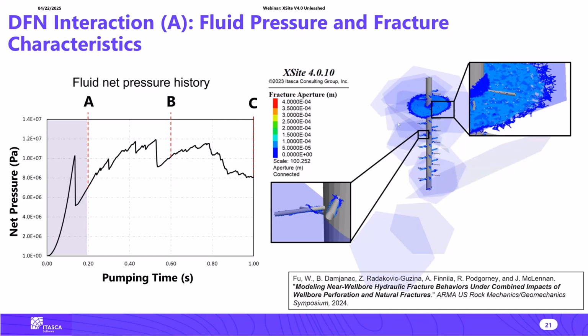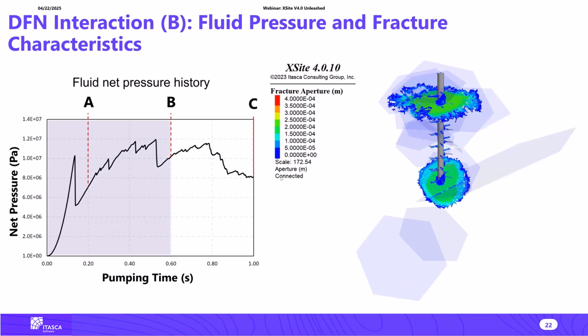However, in this region the fracture intensity is quite large, and these other pre-existing joints arrest and prevent further propagation of the fracture from that pre-existing joint, and that resulted in the pressure increase. That is a typical observation that sometimes DFN results in an increase in the injection pressure because the hydraulic fractures get arrested.